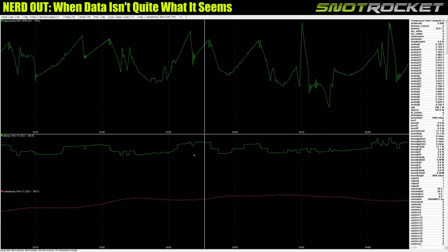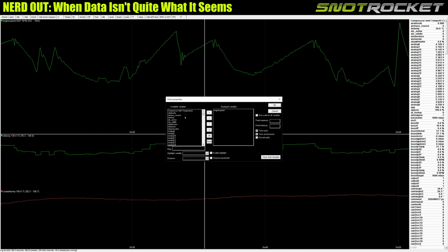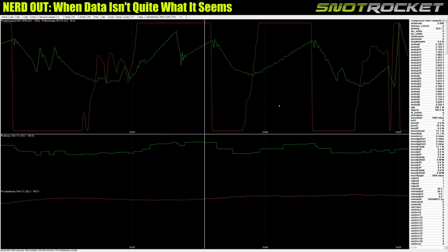And to give you an idea, if we zoom in to just 10 seconds, you can see up here the engine speed's going up. Let me add another chart on here. Now let's put the throttle in so we know when we're full throttle. So this red line now at the top, the second one, is basically the throttle position. And you can see here going full throttle, and then we're going up in one gear, changing gear, going up in another gear.